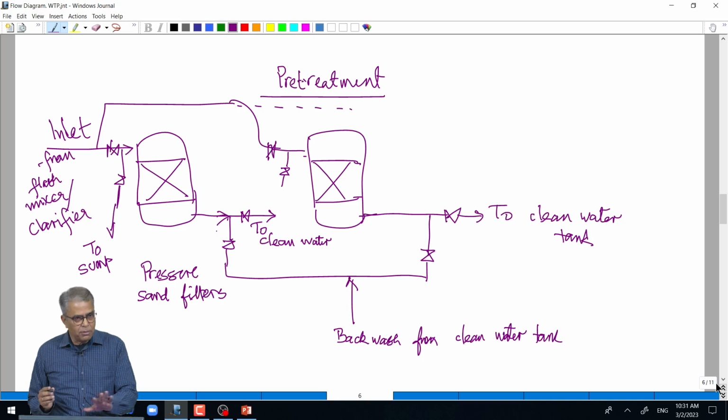So, you treat this with pre-treatment pressure sand filtration. Basically, this time you can't use gravity because the volumes required are horrendous, that is another point. I said earlier that the water recovery is close to 95-98%, whatever water comes practically lands up. Here with sea water, the recovery is only about 45%. Why 45, 48, is a separate topic, but for the present it is not going to be 90, it is not going to be 10, it is 45%.